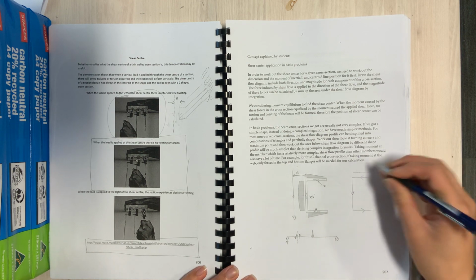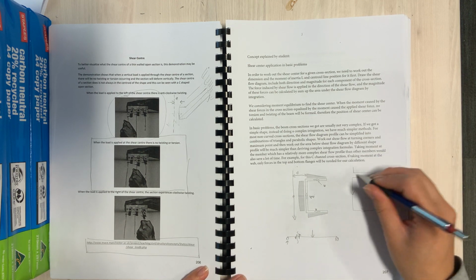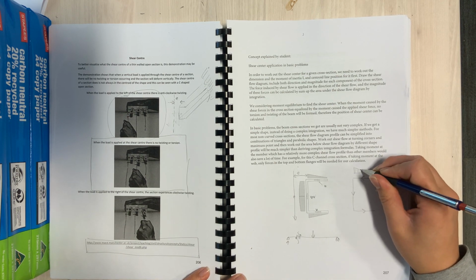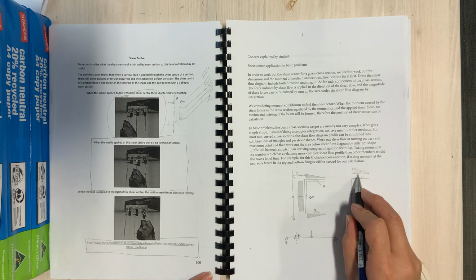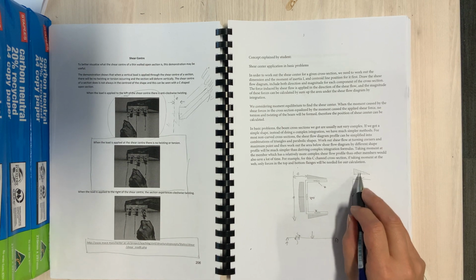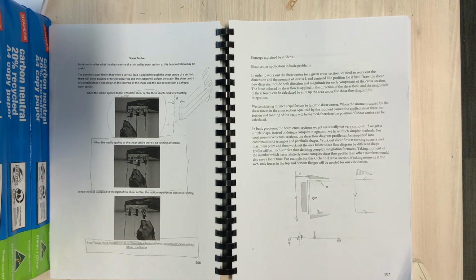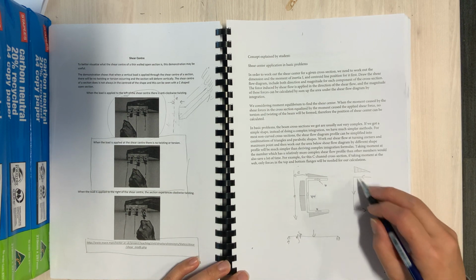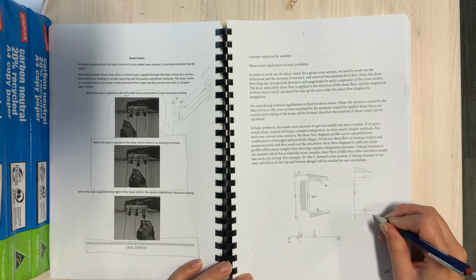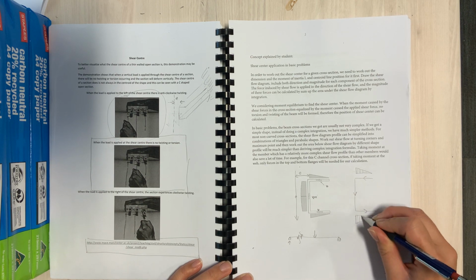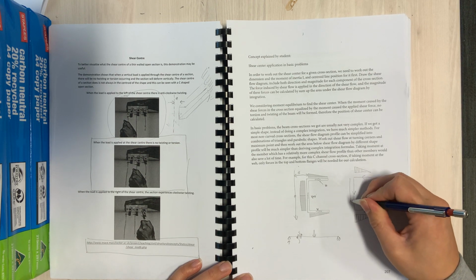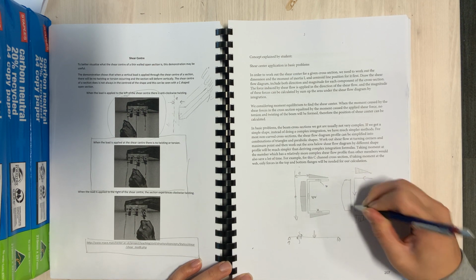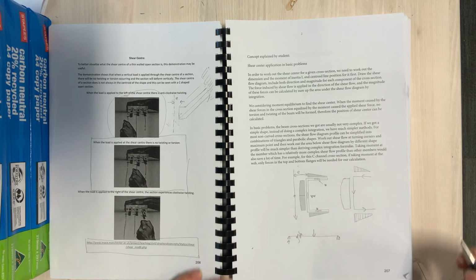They're just related by the parameter t, which is the thickness of the section. So that would be the distribution of the shear flow going through there, and the area under that becomes the force acting in the flange. So that's a triangle, and then this side here would of course be a triangle there. And then down here we'll have a parabolic nature with the maximum shear stress being there.